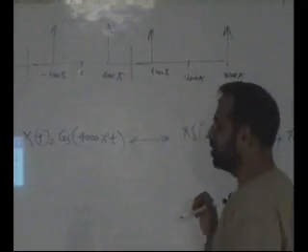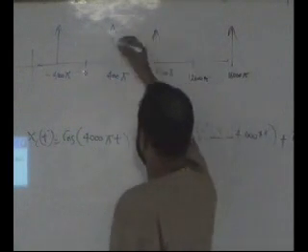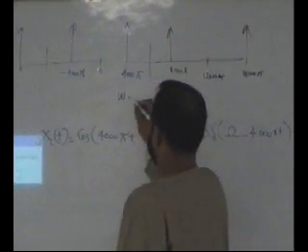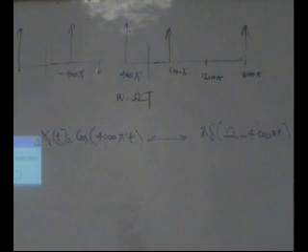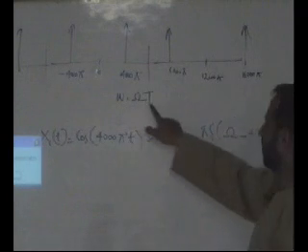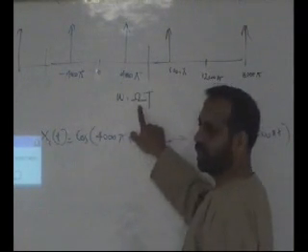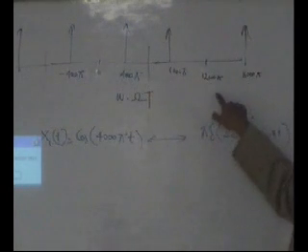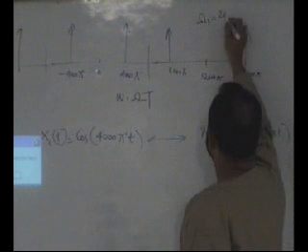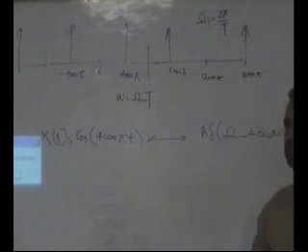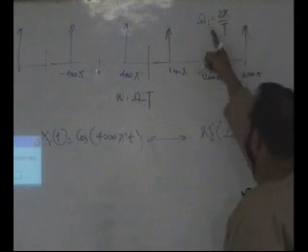So you can actually know what the digital frequency is by remembering small omega is equal to capital omega times T. Using this simple formula will help you figure out exactly what this frequency will map to. This frequency 4,000 pi is omega, and this is 1 over T. This is omega_s, and omega_s is 2 pi over capital T. So you can compute T because 1 over T is omega_s over 2 pi.